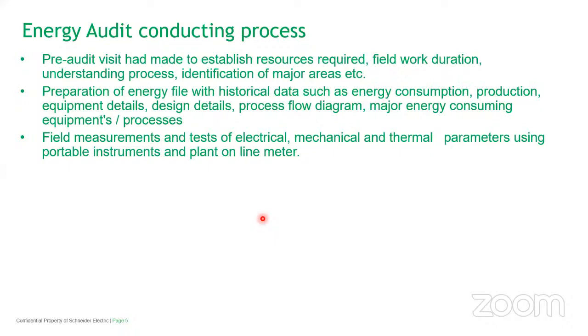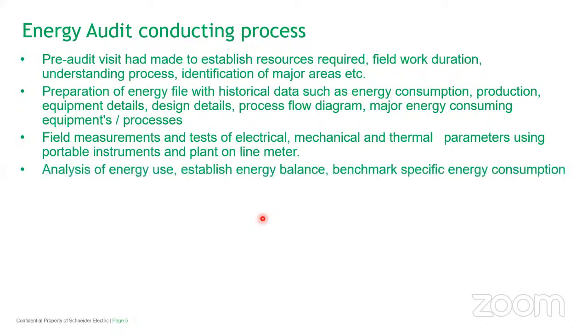These are the instruments we carry, and we connect to the various R phase, Y phase, B phase. Typically, most industries or large buildings will have 3-phase power near the transformers. So we measure the power with a 3-phase. Sometimes if it's a house, it will be single phase also. We can take the measurement through various power meters or power analyzer meters, and this takes the data in terms of data logging.